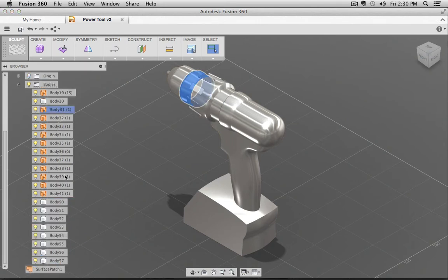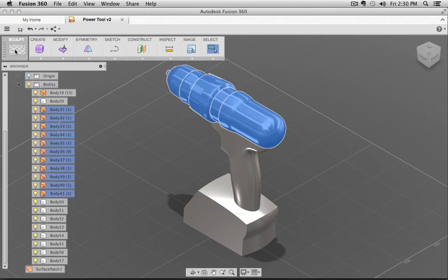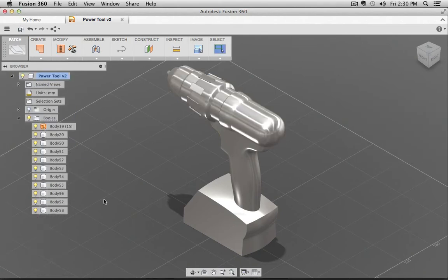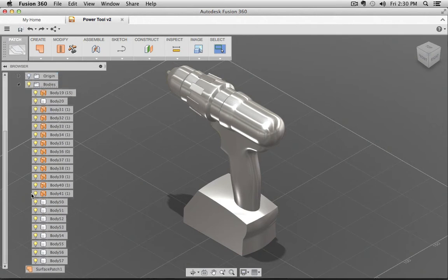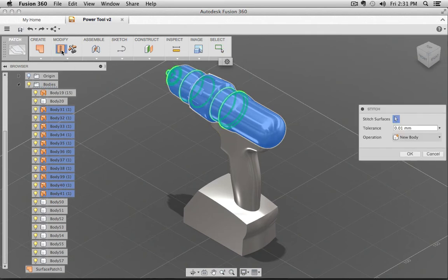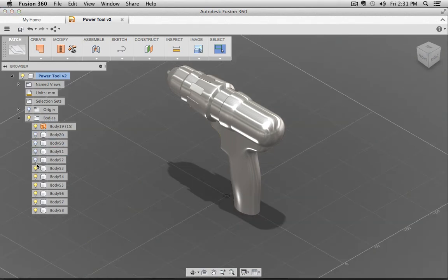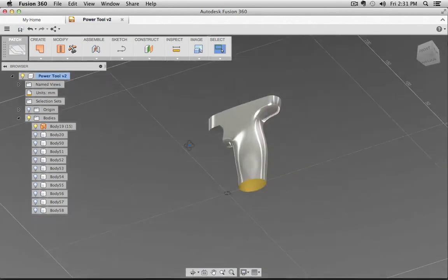And actually, everything from here to here, I am going to join right now through the stitch command. You noticed by doing this stitch command, currently the feature, like the surface patch, which is a feature, so it's interactive, kind of like a modifier, is being applied. So be careful about when you do the stitch command. It bakes it together. So now let's see what we have here inside our design object, scene.